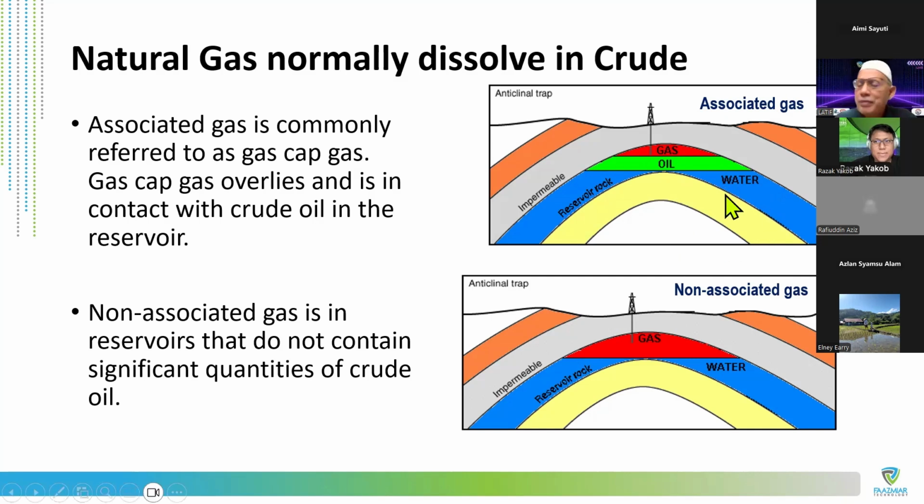But if the water drive system is very weak, then once you produce to a certain volume, the creation of vacuum will deplete the reservoir, and then to a level where there's not enough energy for the oil to naturally flow to surface. That is where you need artificial lift, gas lift or a downhole pump, to really suck the oil because of the depletion that happened.